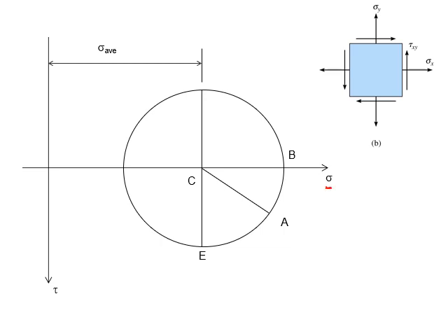So that's sigma. Normally we have megapascal as the stress values. Okay, so we have tau. Also we have megapascal as the unit. And this is positive downwards or counterclockwise. Okay, and so up here is clockwise or negative.